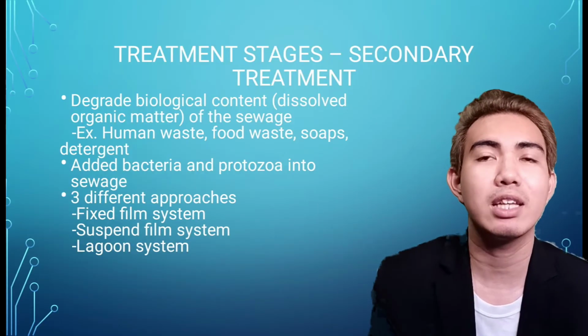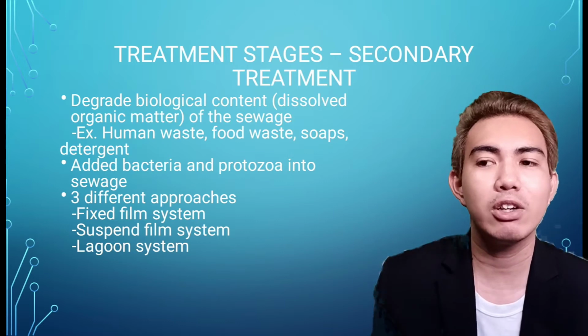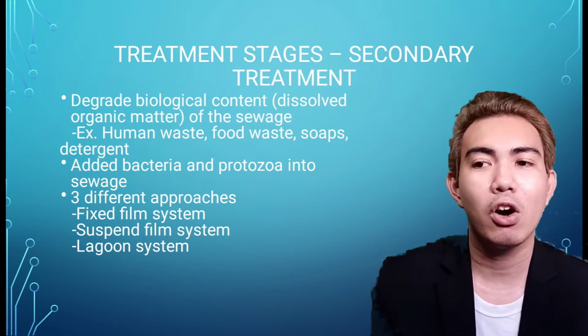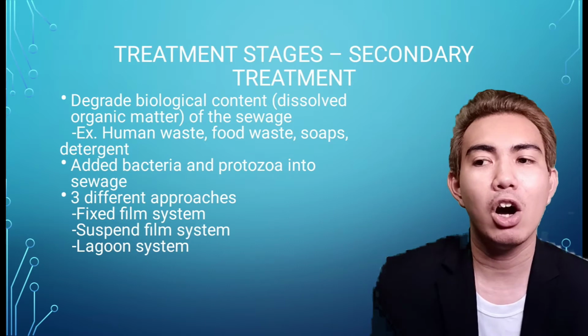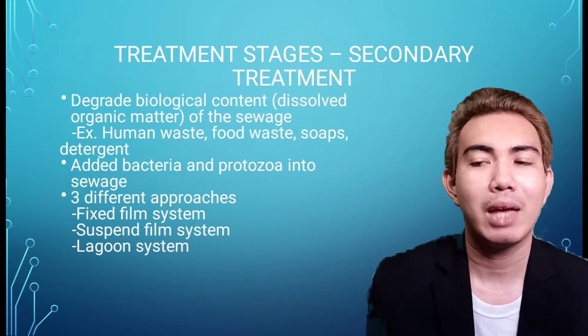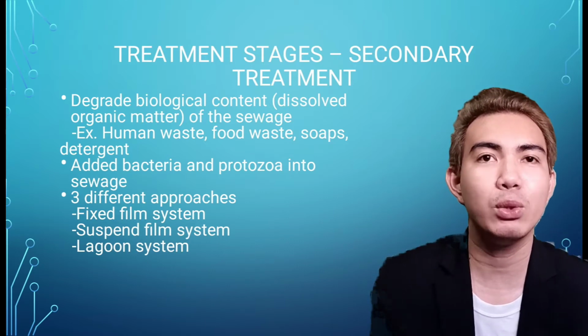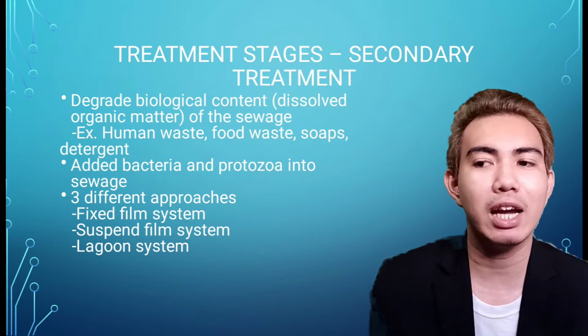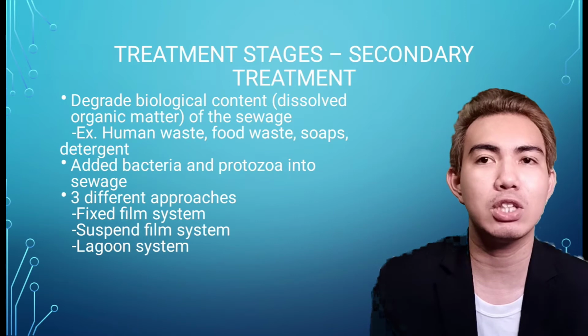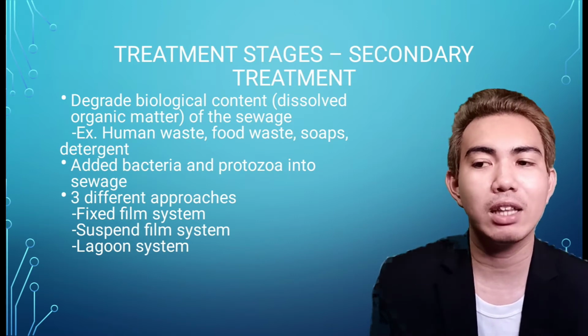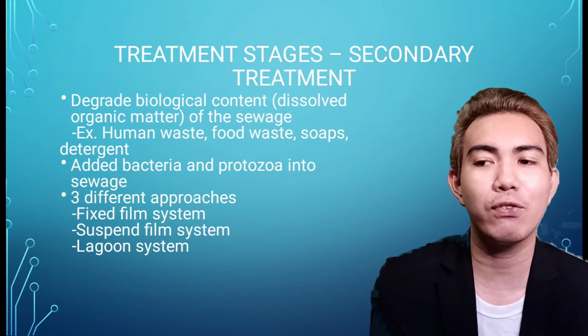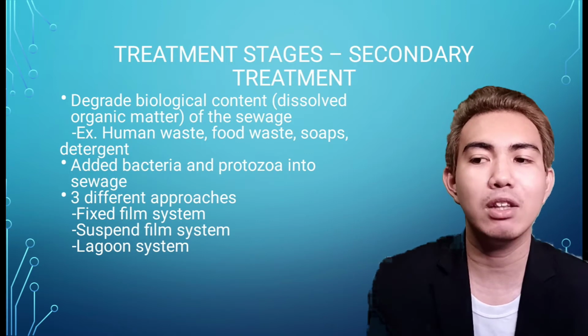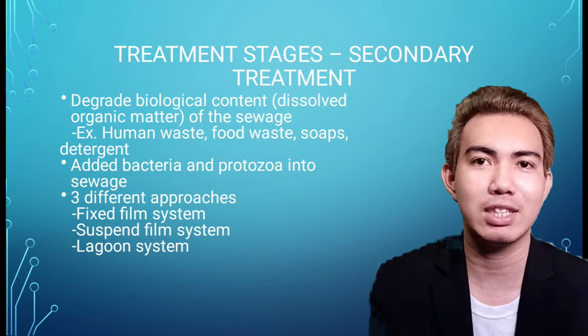Treatment stages. Secondary treatment. Degradation of the biological content or dissolved organic matter of sewage, for example human waste, food waste, soaps, and detergents. Bacteria and protozoa are added into the sewage. Three different approaches: we have the fixed film system, suspended film system, and lagoon system.